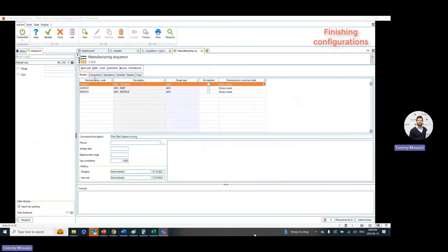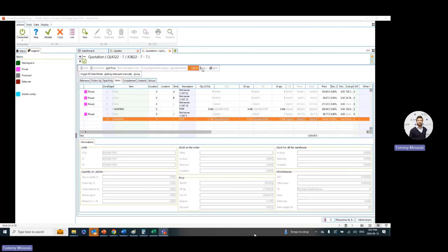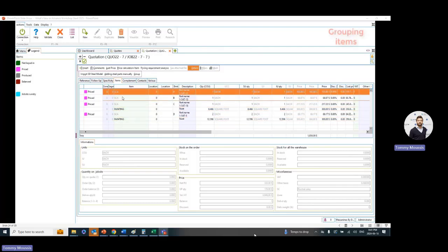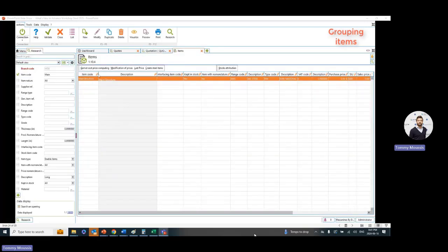Now, if we take a look at the manufacturing sequences, here we'll see that in our manufacturing sequences for steel connection parts and steel connection plates, these are the features that group together raw material items and operations. We've added the additional components for galvanization and paint. So now once our import mechanism reads that there's a coating applied, and we're using those SKUs for paint or galv, it'll then compile the additional costs. If no coating is applied in Advanced Steel, it will not execute the function.